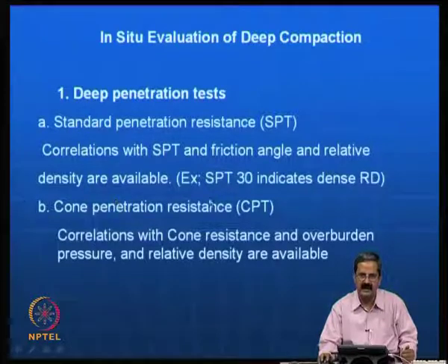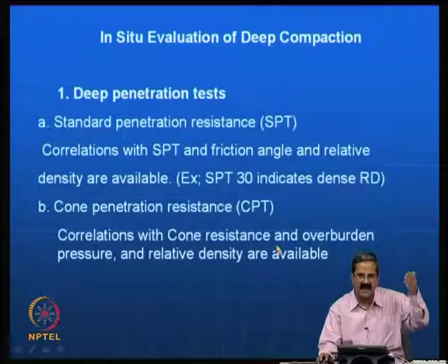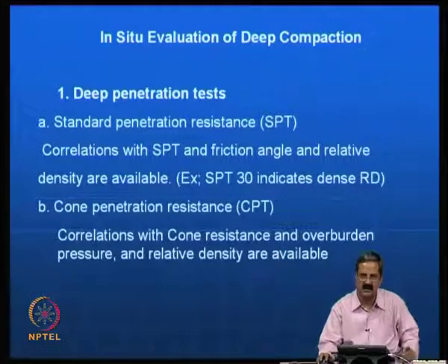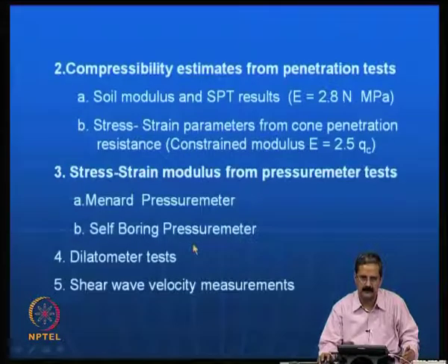Here again you have correlations with cone resistance and overburden pressure. In fact, the higher the overburden, the higher the resistance and the higher the relative density. So, you have some literature available which will clearly tell you if the density is very good. Then, as I just mentioned, compressibility estimates from penetration tests.